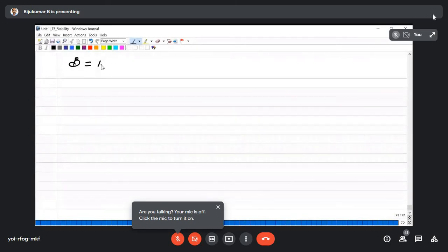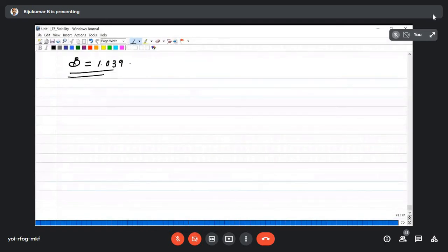Okay, clear. So this is the pattern. For this particular system, the zeta is obtained as 0.456, so it is an underdamped system. First there will be oscillations, overshoot, undershoot. Finally, after a settling time, it will reach the steady state value. Okay, so we will wind up the second order system here.